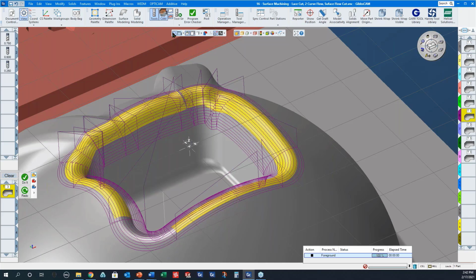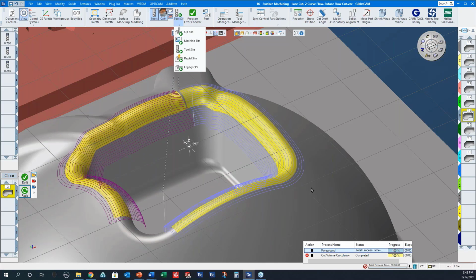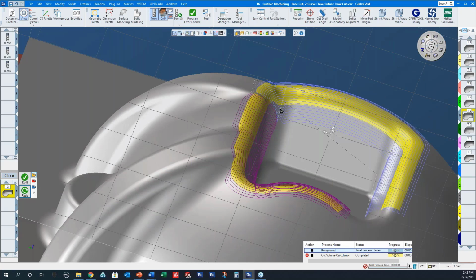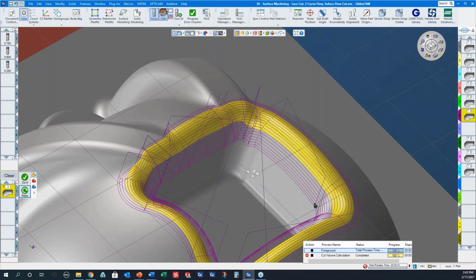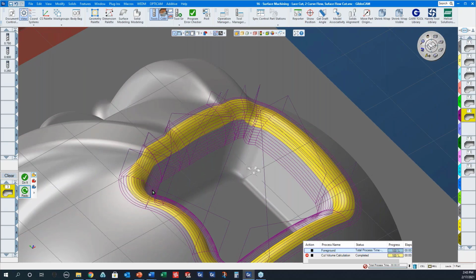So if I just redid that toolpath just like it is right now, it actually creates two smooth toolpaths, but I didn't cut those areas. But watch this. If I select those as well and redo it, it now breaks every one of them into individual toolpaths.